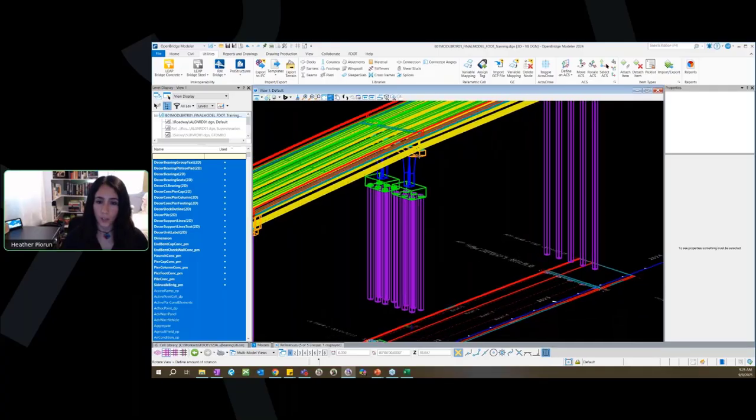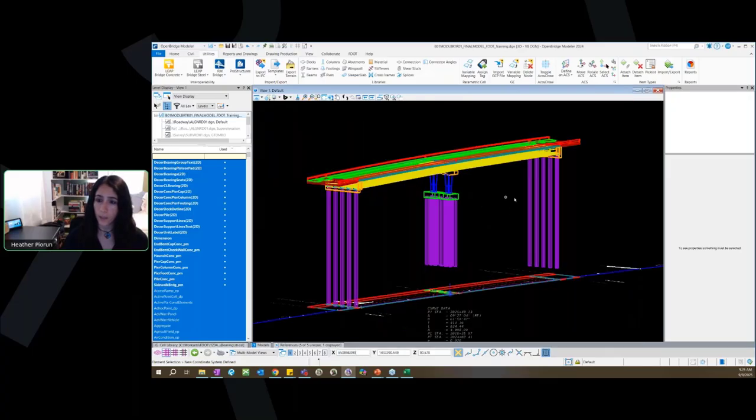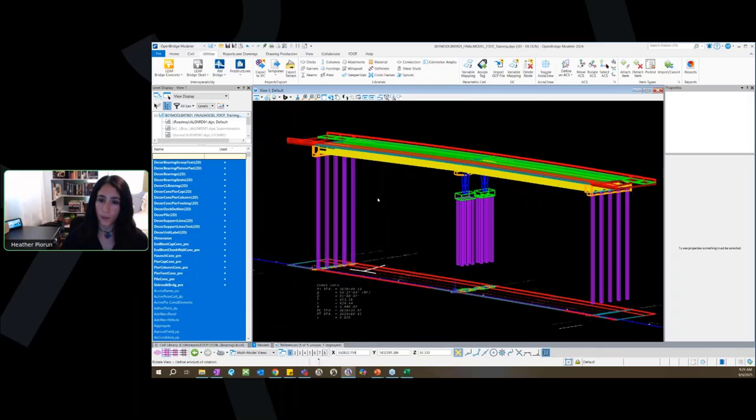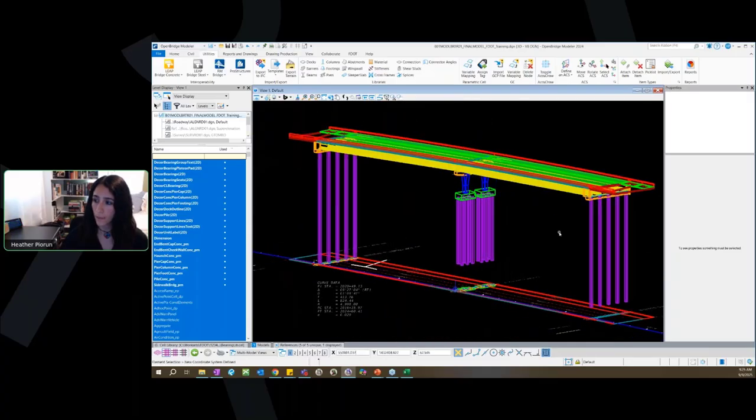Very helpful targeted rotation. You can also do dynamic rotation without the crosshairs, which you can do either click and hold, use rotate view, or what I generally do is hold shift and then use your click wheel, and that'll also give you a dynamic rotation there.